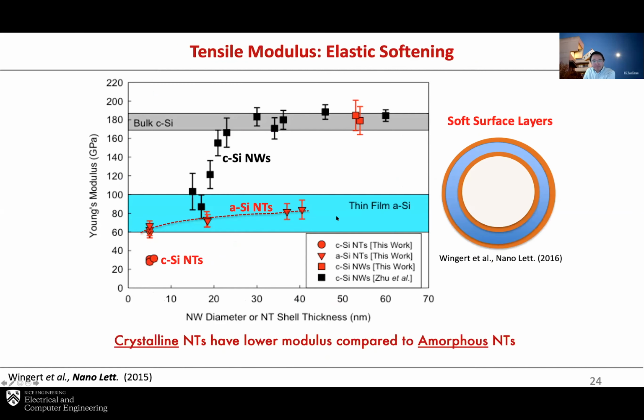What happens is we also realized that when you have very small tube thickness, not only do you have a very short phonon moving path because phonon will be scattered by the surface of the tube, both the inner and outer surface, but you also have impact of the size on the mechanical properties, in specific Young's modulus, and that will actually also dictate the speed of sound in the material or acoustic property of the material.